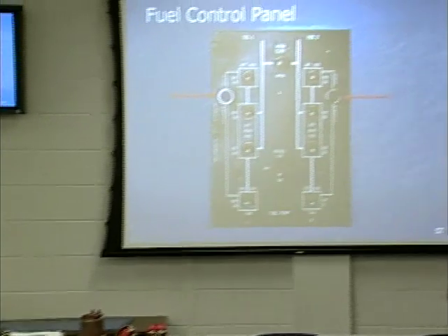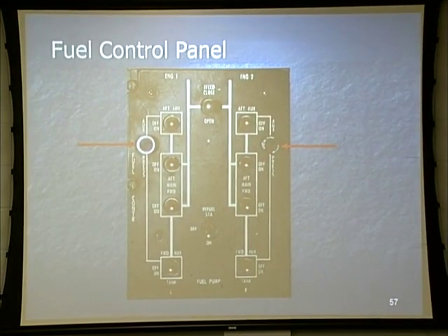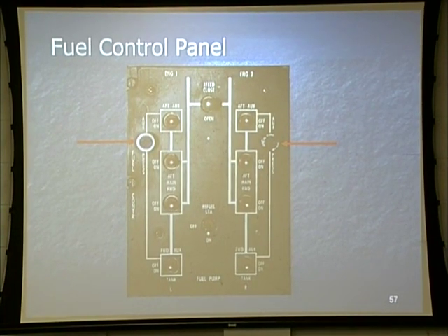Our aux fuel pressure lights. When any one of the aux tanks has less than 10 psi plus or minus 1, and plus or minus 1 is always a parameter for everything. Okay? So 10 psi plus or minus 1, if it drops below that pressure. Now keep in mind that we have one pressure light, but it's monitoring both tanks. Both the left aux tanks and both the right aux tanks.